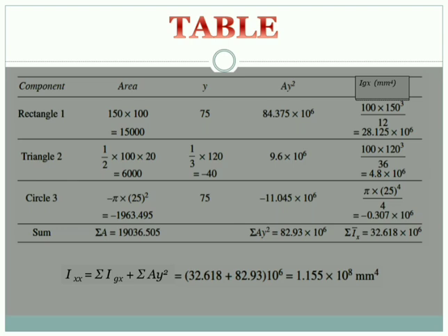There is no need of calculating Igy, because moment of inertia is asked only about the x axis, which is given in the figure. The formula I am using for the rectangle Igx is bd cube by 12. These formulas are independent of any distances; they are only dependent on the shape of the figure. Bd cube by 12.